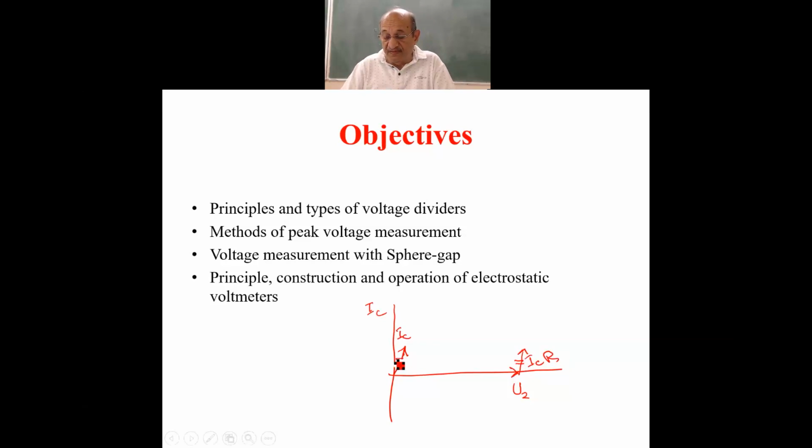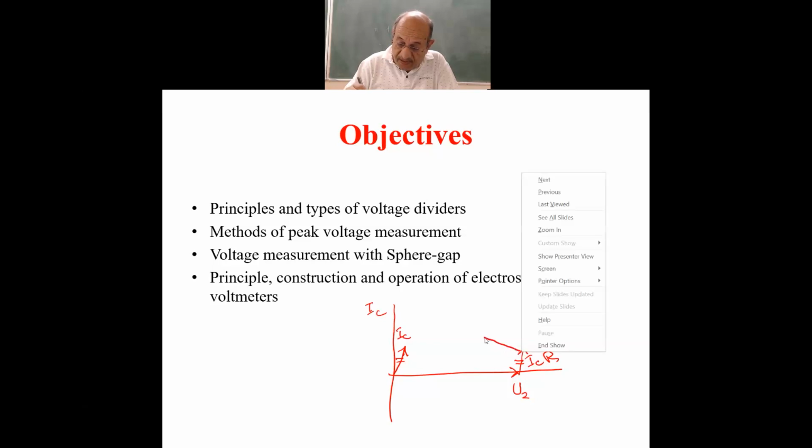The resistive drop, the active power loss, or the resistive current loss, that can be determined. And then you make the capacitive reactance drop, that will be this way, isn't it? Now at 90 degrees to this.